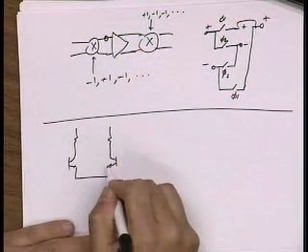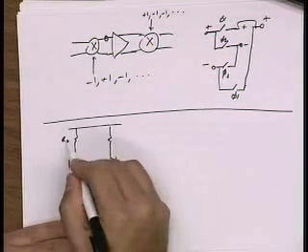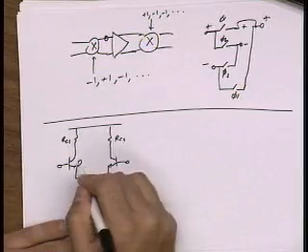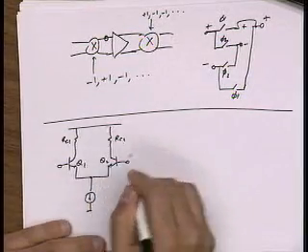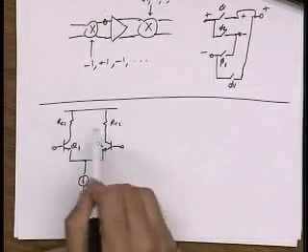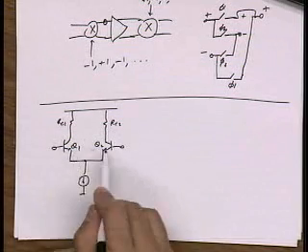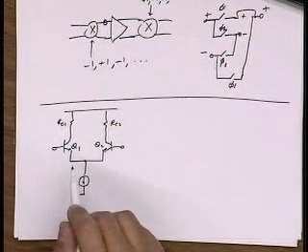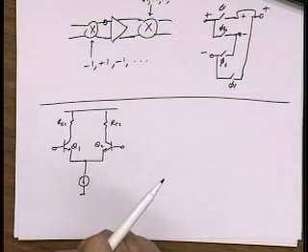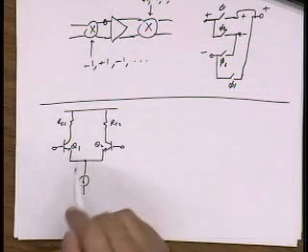And I'll take a really simple topology, let's say a differential pair that we looked at just right now, and let's actually calculate the offset voltage for various quantities that can vary. So for instance, we know that RC could vary, right? We also know that these transistors are not perfectly matched, right? Their dopings could be slightly different. Their geometry could be slightly different. We're just going to lump that all into the saturation current of the devices.